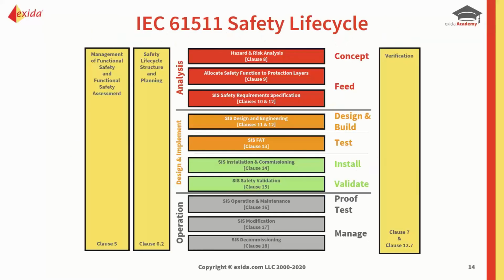And typically when we're looking at the life cycle, when we're in the design phase, most of the time we focus on the hardware aspects because we're looking at, okay, can we meet the PFD average or the PFH? Can we meet the architectural constraints, and is the systematic capability good enough for the target SIL?